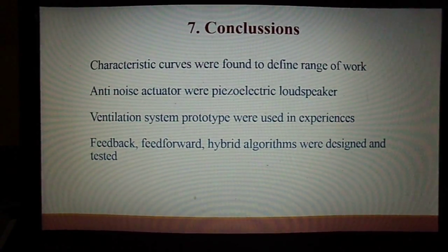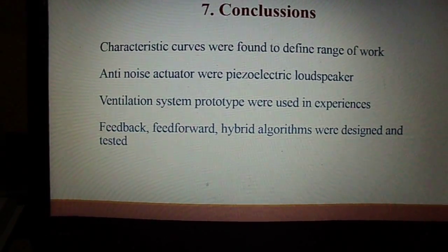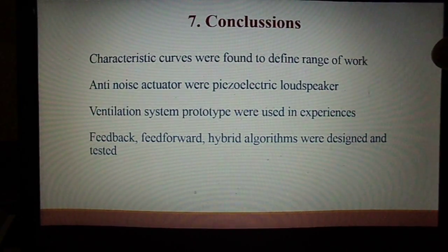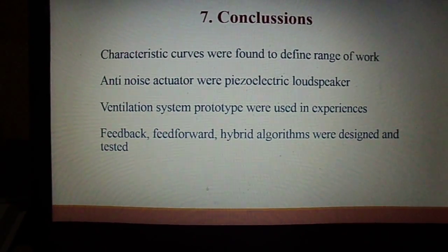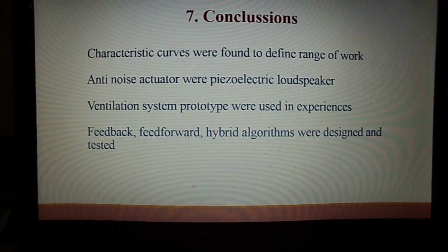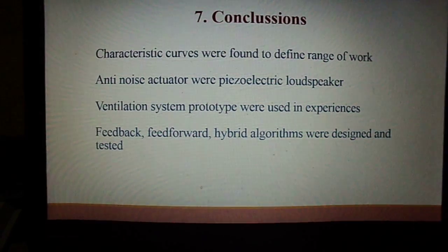Conclusions: characteristic curves were found to define a range of work. The piezoelectric loudspeaker, as anti-noise actuator, was analyzed in its operating range. A ventilation system prototype was used in the experiment, and feedback, feed-forward and hybrid algorithms were designed and tested.